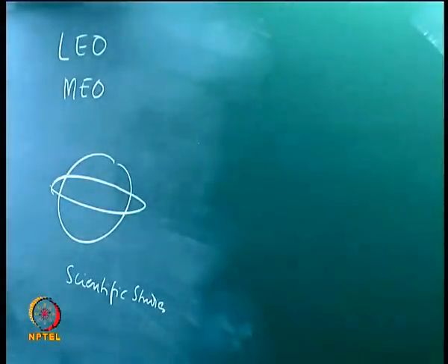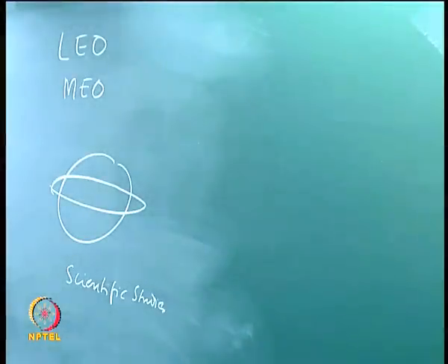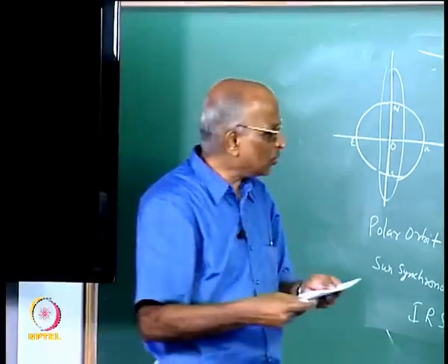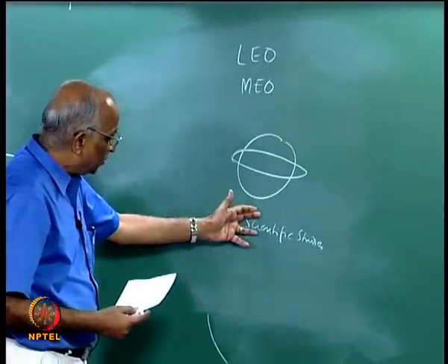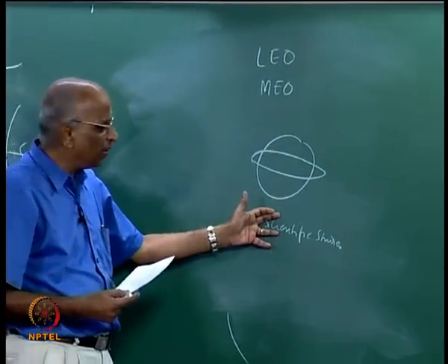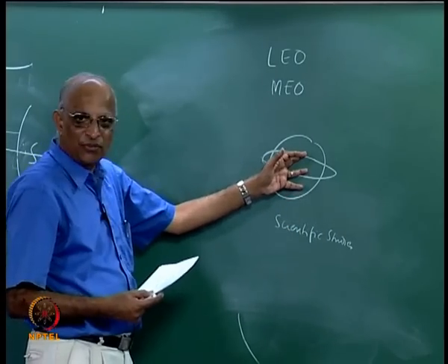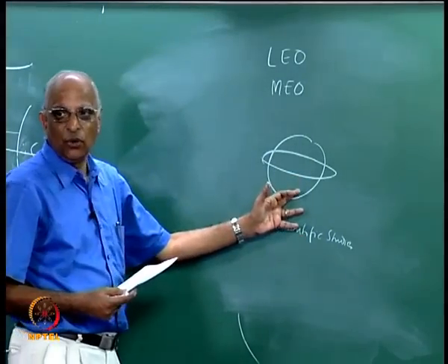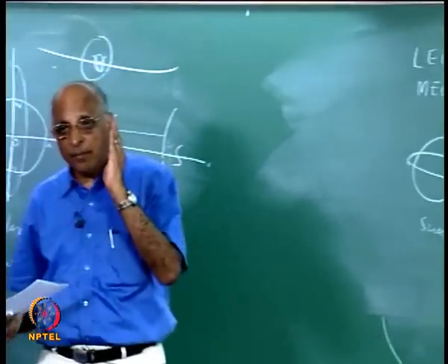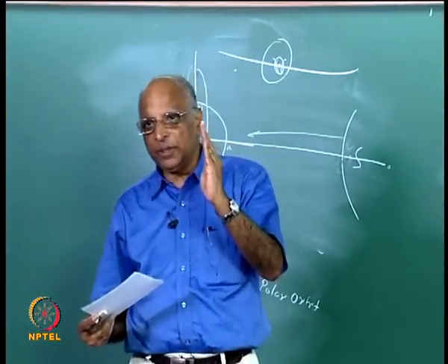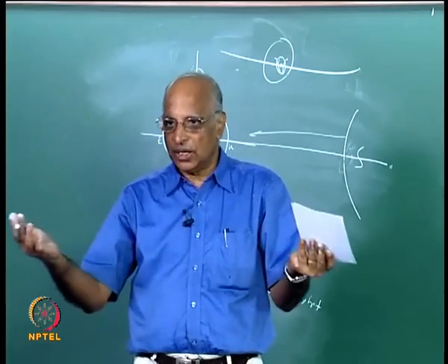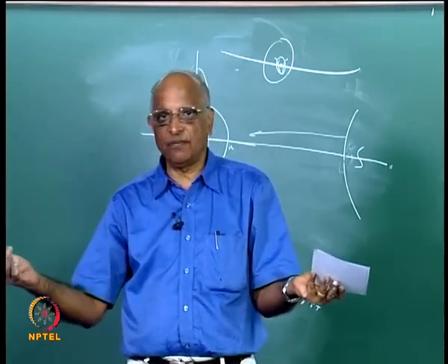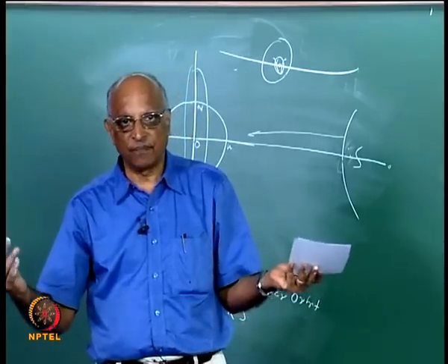In the stratosphere you have wind, and we would like to find out the wind velocity. We were also told there are charged particles available in the stratosphere. Maybe I would like to measure some of these things, and that is how the low Earth orbit is used. But there is a limit to the low Earth orbit. Typically it has to be greater than 300 to 400 kilometers, otherwise the atmosphere will cause drag.